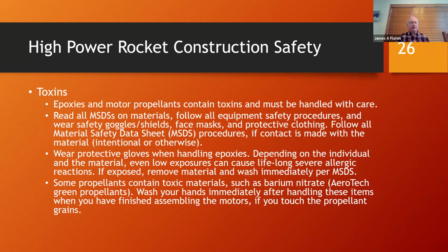Generally speaking, always wash your hands after you do any of these tasks, even if you're not working with something that you believe is toxic, and always, for sure, if you know that it is toxic. This also applies to soldering. If you're soldering with solder that contains lead, don't breathe in the smoke that comes off of the rosins, and wash your hands after you're done. And then, of course, for soldering, don't burn yourself and certainly don't burn anybody else.